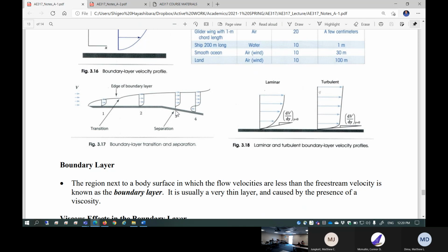So we always have a trade-off of two things in viscous drag. One is, if the flow is attached on the surface, skin friction drag coefficient. The other one, once the flow separates from the surface, is pressure drag due to flow separation. Those two trade off. Those two added together is called profile drag. Do you remember those from aerodynamics?